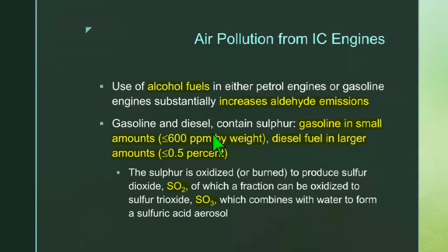Gasoline and diesel contain sulfur. Gasoline in small amounts, less than or equal to 600 ppm by weight. Diesel fuel in larger amounts, less than or equal to 0.5%. The sulfur is oxidized or burnt to produce sulfur dioxide, SO2, of which a fraction can be oxidized to sulfur trioxide, SO3, which combines with water to form a sulfuric acid aerosol.